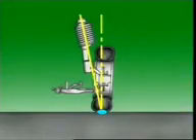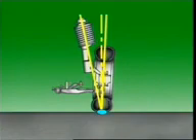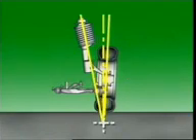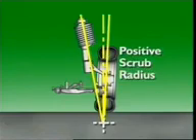With a vertical steering axis, no self-centering would occur. The wheel would pivot on a radius with the steering axis as its center. This would introduce a turning moment on the wheel. Road shocks would be transmitted back to the steering wheel, and steering would be difficult to control. Steering axis inclination brings the pivot point close to the center of the tyre contact patch at the road surface.